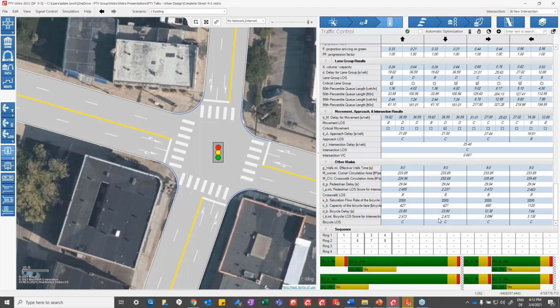And you can see within this unmitigated road, without the road diet, we have a level of service C, and we have an intersection score of about 3. And then the bicycle delay is 12 and 7. So within this example, it's not bad. It's actually working okay. Of course, I have a low volume that I put in, but it's not bad for bikes.